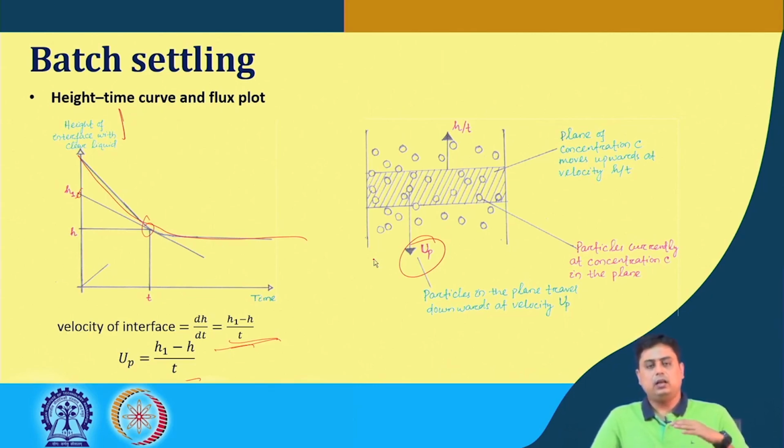At this time t, there is a propagation of higher concentration suspension upward, because the clear liquid and suspension interface is moving down, while the suspension and sedimentation interface is moving upward.